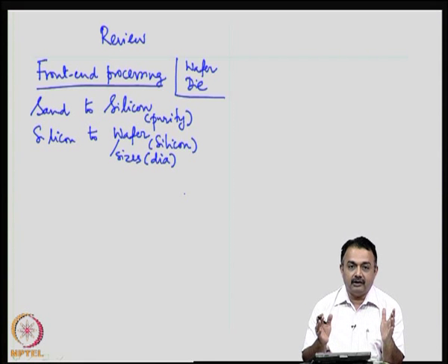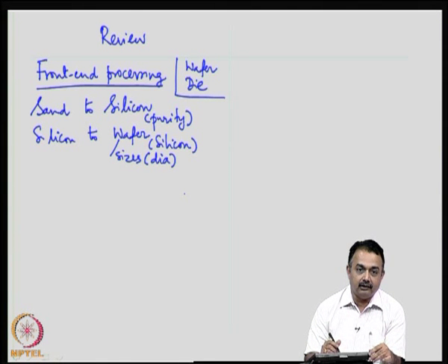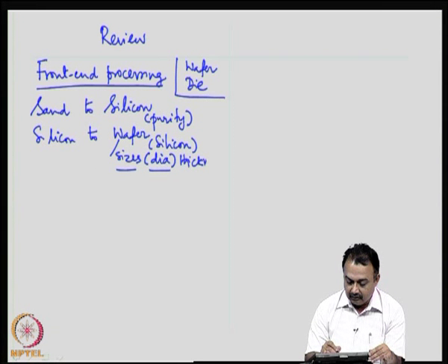As the diameter increases, you are going to get more dies accommodated on the wafer, but at the same time the yield percentages have to increase, otherwise the manufacturing costs are going to be larger, accountability will be very high. Therefore, whether it is a silicon or a compound semiconductor or other material, sizes are very important. The thicknesses are also very important.